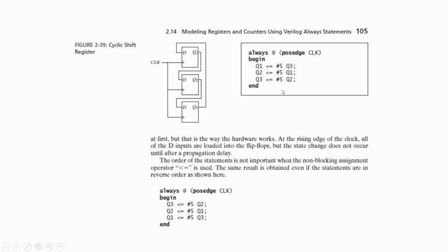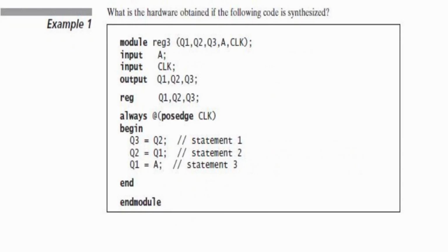So that is the main difference between blocking and non-blocking operators. Just remember this fact: blocking operators are used for developing combinational logic, and non-blocking operators are used for developing sequential logic or sequential circuits.